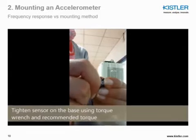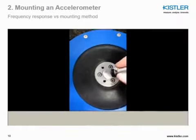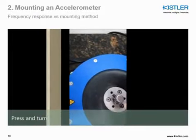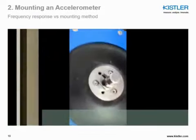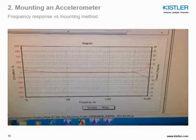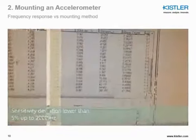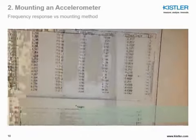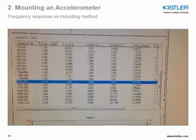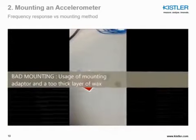Don't follow my lead here. We press and twist to have it fastened on our shaker, and then we run the test. And here we're going to see a deviation of 5% at 2000 Hz. So the frequency response is getting lower and lower, adding those mechanical filters in between the sensor and the surface.